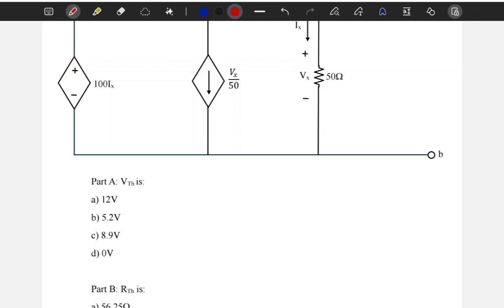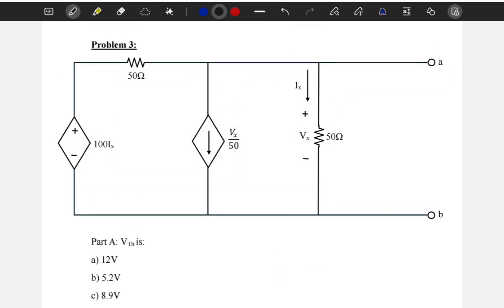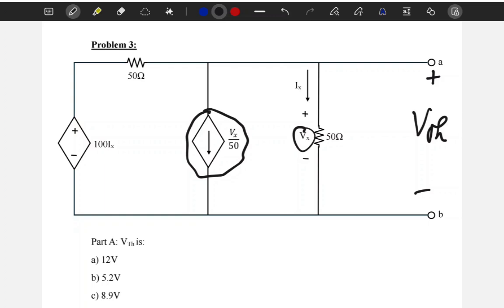Okay, before I go back to the notes up there and discuss case 3, I need to ask, what is Thevenin? Right away, you can guess Thevenin. The argument is that the entire circuit doesn't have any independent source. So there's no source of energy without dependence on another thing. In here, we have this dependent source, for example, it depends on Vx. But Vx doesn't really have a source. Again, this source right here is dependent on what Vx is, but Vx has really no origin. It really isn't driven by an independent source.